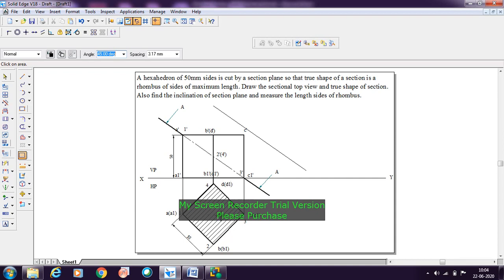The hatching indicates it is like a bandage for the wound. So don't show the other portions other than the cut portion here. Now in this case, when you see from the top, this entire portion is cut here. So in the top you can see that 1, 2, 3, 4 is cutting the entire object in the top view. So for that you need to show the hatching here.